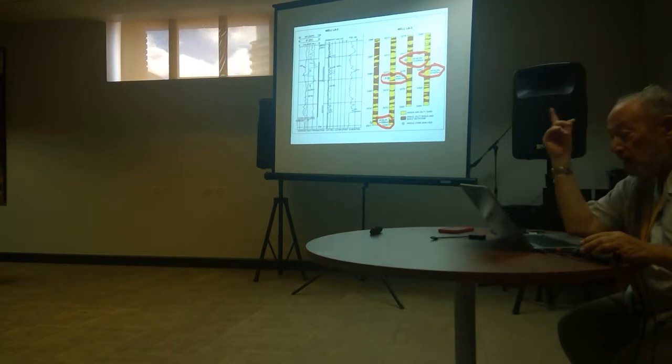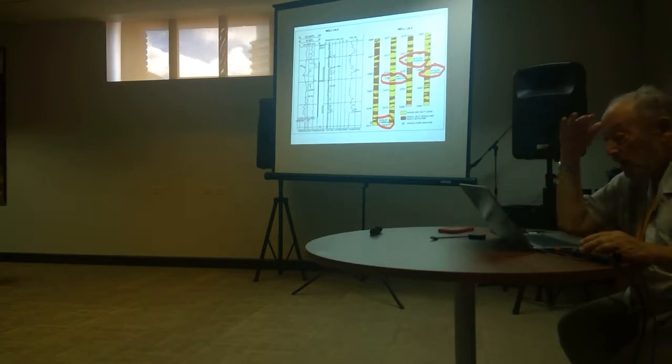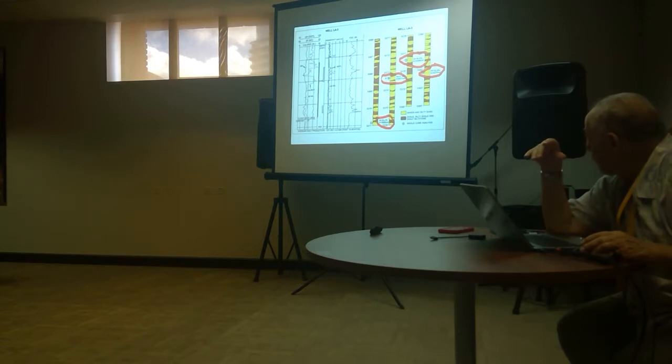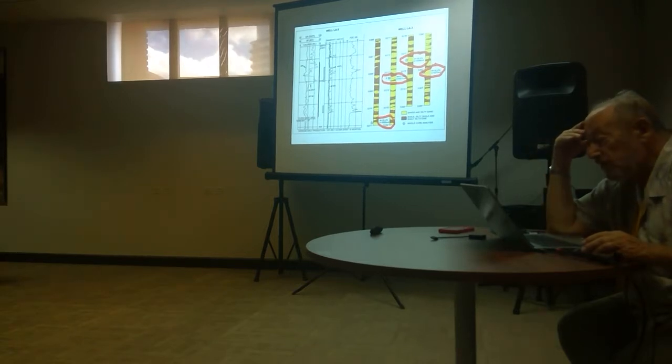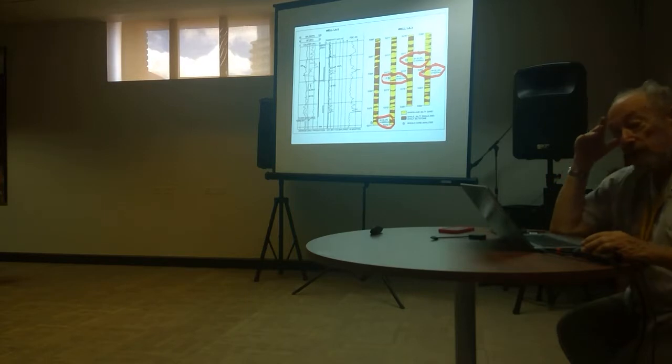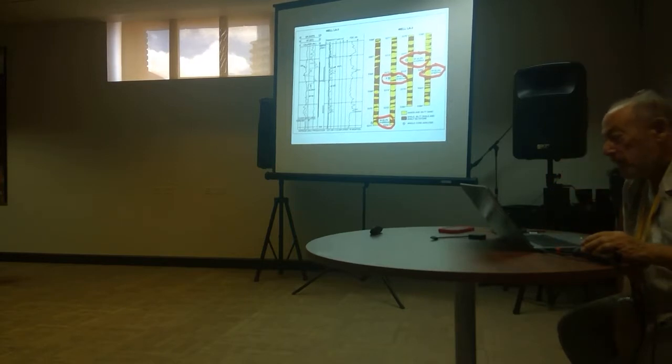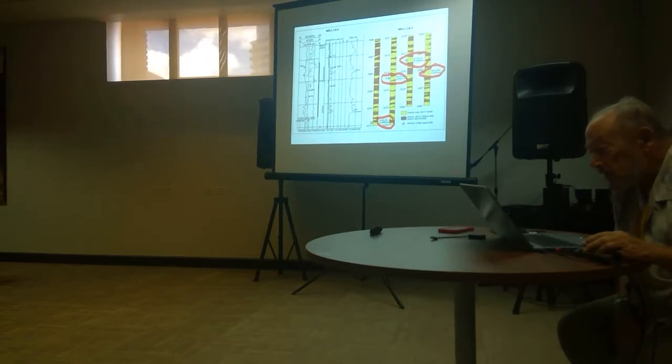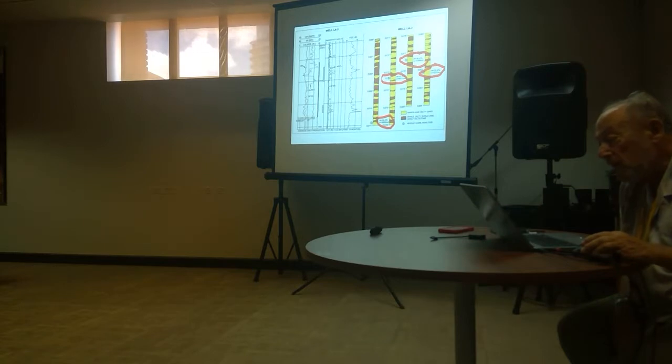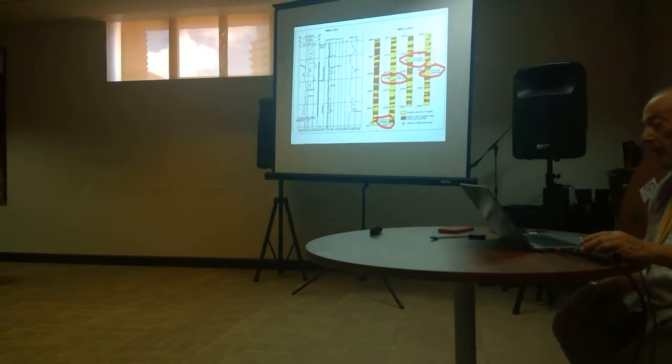Okay, so you've got 4 core plugs, and if you look, if you can see this, the porosity is not very different between those 4, all about 30% porosity, but the permeability is quite different. Here we get 3,990 millidarcies permeability, 4,011, 4,289, and 5,270.